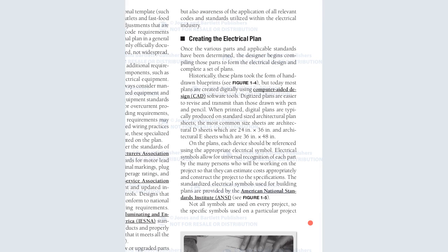Before the electrical engineer can power the circuit, or power the diagram, they have to understand the scope. Remember, we talked about understanding the scope. In understanding the scope, you need to know what is the work of the room, of the building. What is it going to be used for? Is it going to be used for residential? Commercial? Or a workshop or an industry?